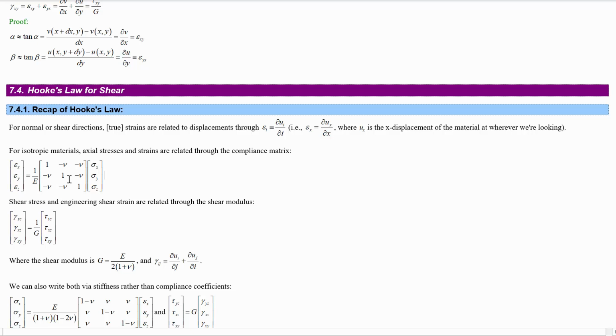Before, we said that the full Hooke's law, considering different axis coupling for a material, relates the stresses in the normal directions to the strains in the normal direction via this matrix here. So what matrix would that be? It's the compliance matrix, because higher compliance will mean more strain for a given stress. So this is the one that we have the symbol S for because of that weird non-intuitive symbol assignment that we're using in statics.